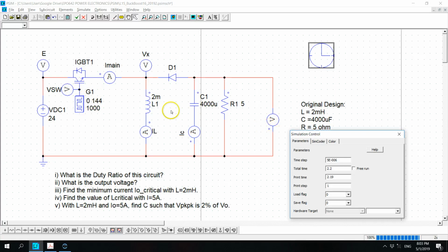And then of course, when you use a large capacitor, you need to understand that the circuit takes a longer time to get into its steady state, right? Because you only analyze the circuit when it reaches the steady state. Therefore, your output voltage is stable. You get the inductor current is symmetrical. The output voltage is stable at the average value.